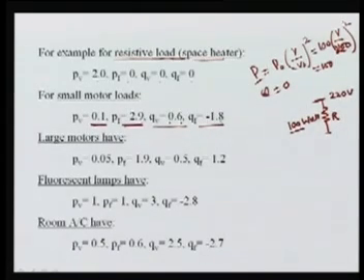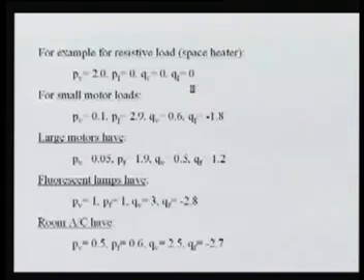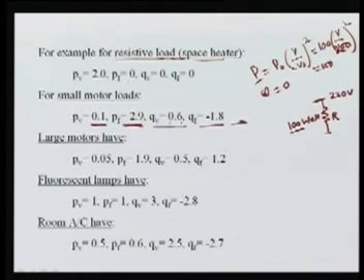What does it mean? It shows that for motor loads, no doubt it varies with the voltage, but the variation is more on your frequency, that is 2.9. This is a huge contribution. If you see here in the P, this value is very small and this is very high, so this ratio is very dominant. And thus for small loads, they suggested these values can be taken.